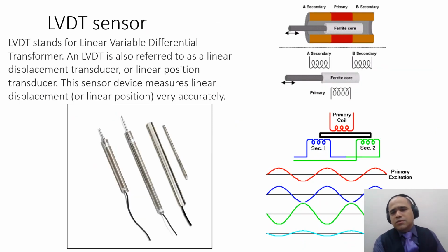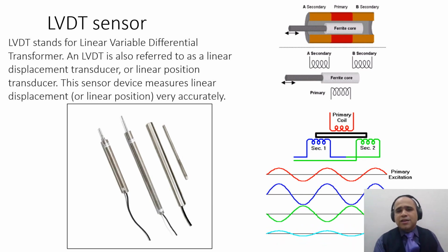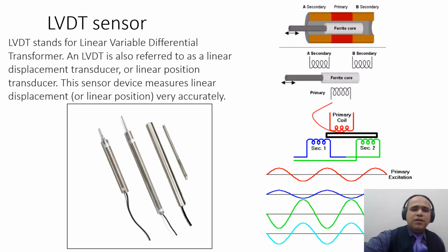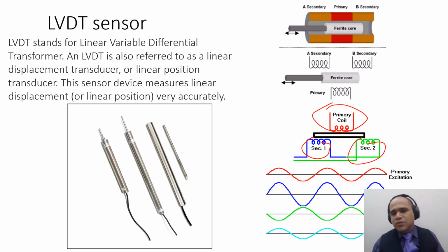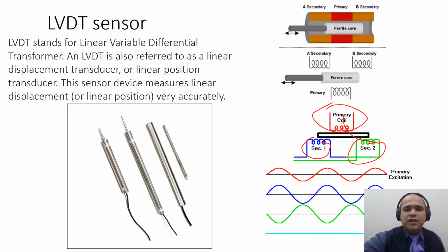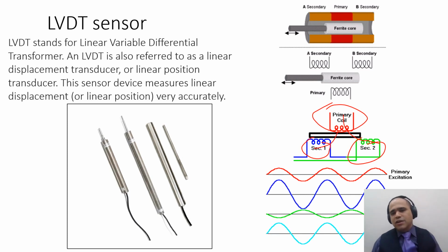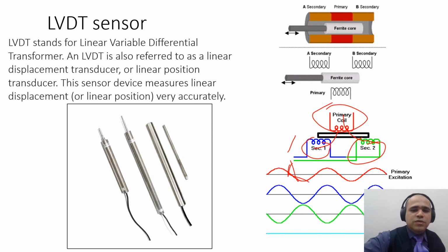The simplest sensor is the LVDT, used to measure displacement. It is basically a primary coil and two secondary coils. Whenever you move its core, it changes the amount of magnetic field getting into secondaries 1 and 2, and we measure the difference signal between the two secondaries.